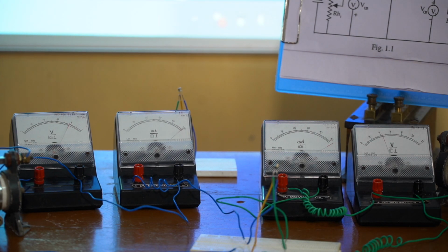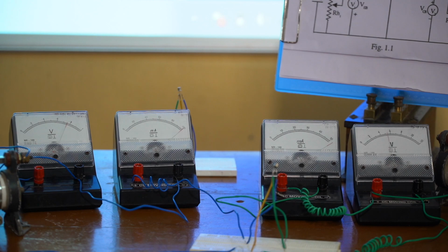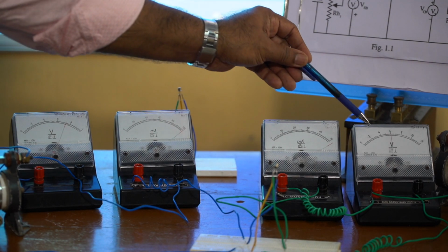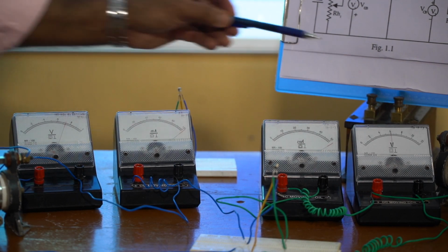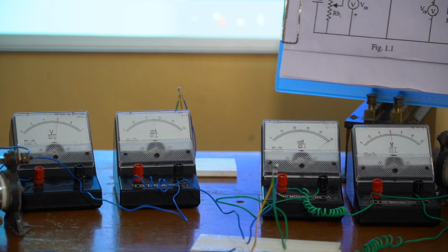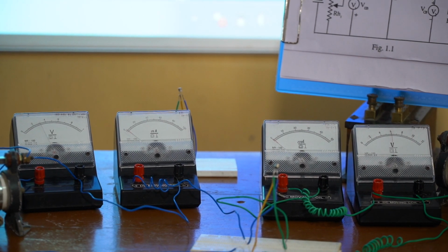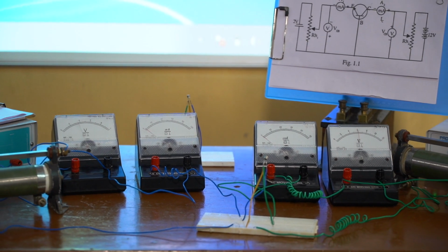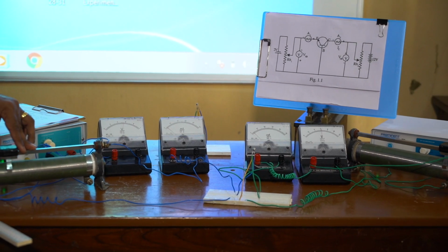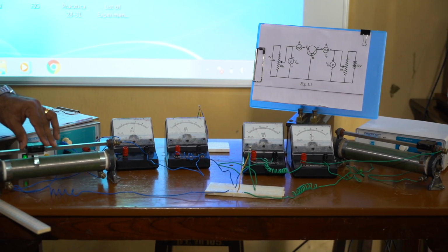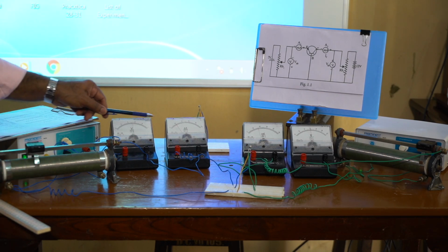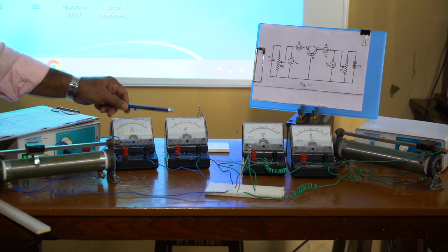We can change the value of the output voltage VCB to a value of say 6 volt. We are taking 6 volt here. Now again the input side is changed. So we are starting with say 0.1 volt. We are getting IE 0. For 0.4 volt it is also 0. For 0.5 volt it is 0, and for 0.6 volt it starts. Now for 0.6 volt of VEB we are getting IE equal to 10 milliampere.